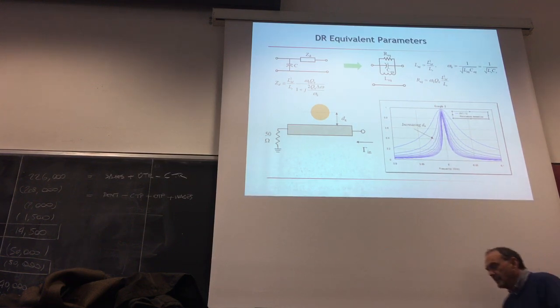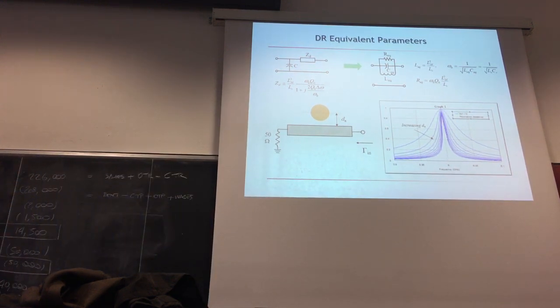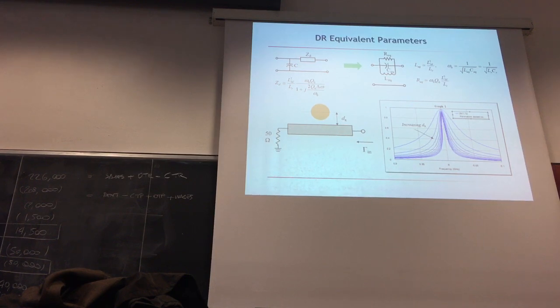Okay, let's see in what way we can exploit this. In other words, how we can exploit the fact that only around the resonant frequency, that is when the electric resonator is coupled to the microstrip, we can have a very large reflection coefficient. The idea is that we can set the parameters of our oscillator in a way that only when this gamma in is close to 1, the oscillating conditions are verified.